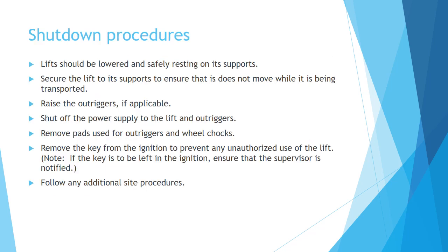Shutdown procedures. Lift should be lowered and safely resting on its supports. Secure the lift to its supports to ensure that it does not move while it is being transported. Raise the outriggers if applicable. Shut off the power supply to the lift and outriggers.